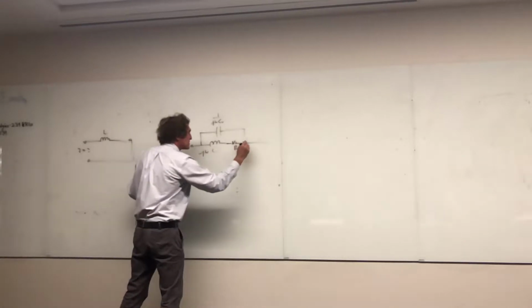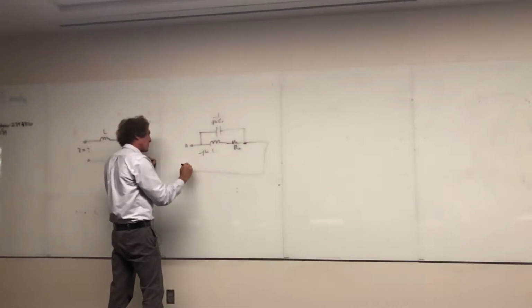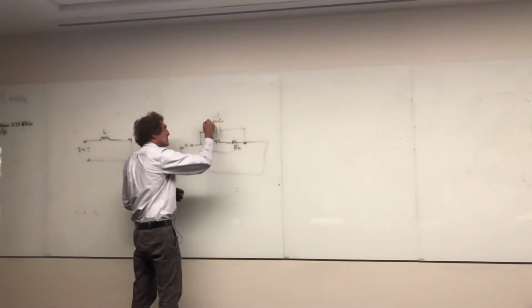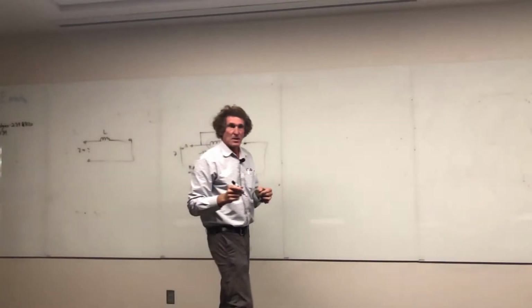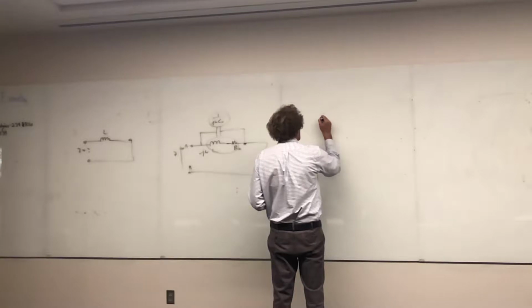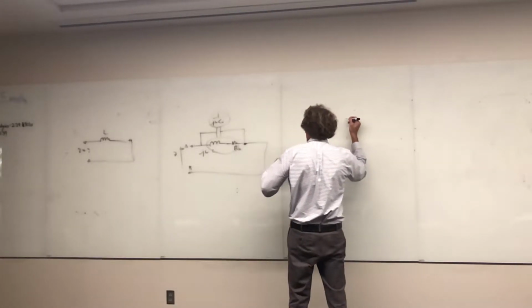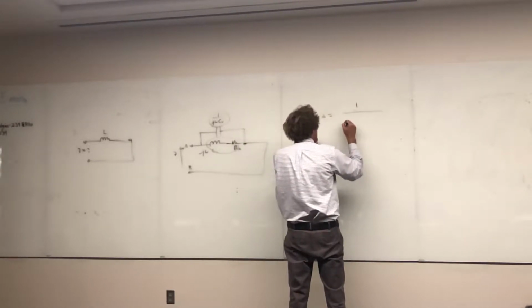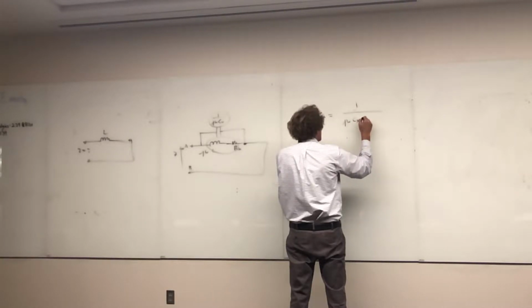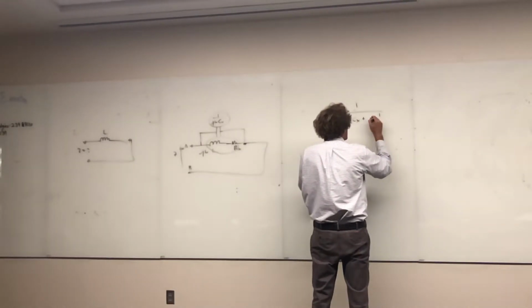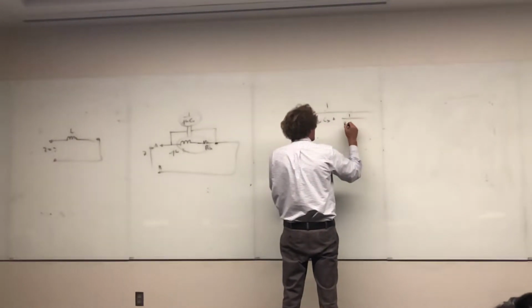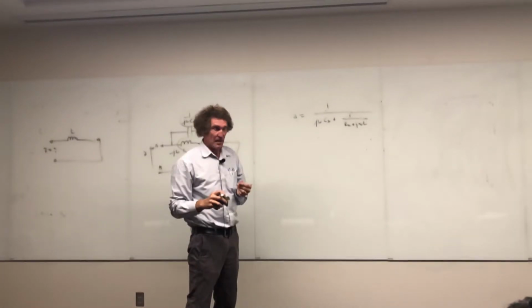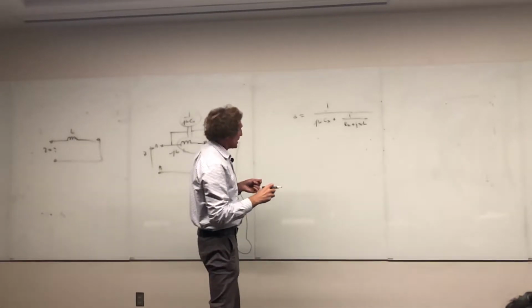So when we look at the impedance between the ends right here and we measure Z, you can see it's going to be this in parallel with this, right? You agree with me? So you can say that Z is equal to, depending how you want to do it, 1 over (1 over j omega Cx, plus 1 over Rx plus j omega L). That would be the actual impedance of that thing, and that should look right.